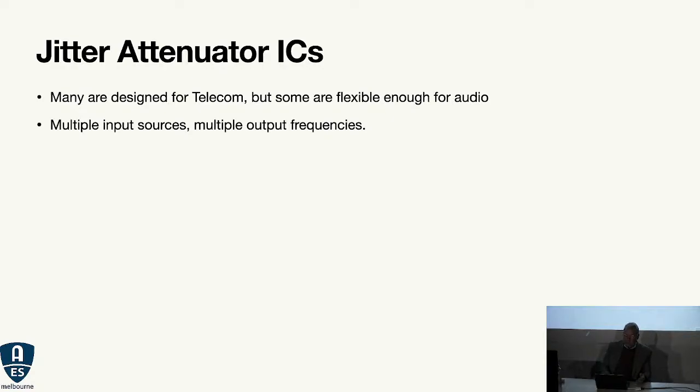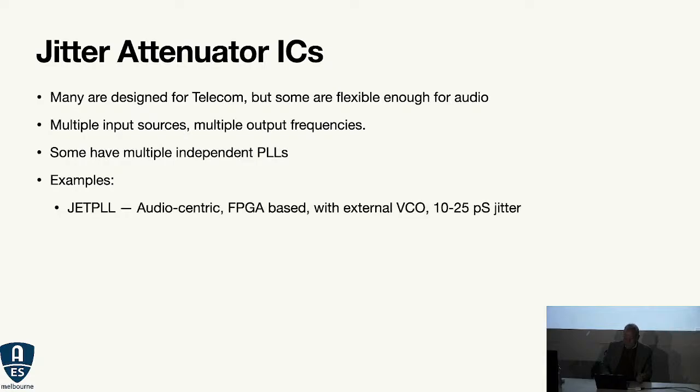These typically have multiple inputs, so you can select different sources. They have multiple output frequencies, so you can get all your different audio clocks out of one chip. Some of them have multiple PLLs that are completely independent, and that can do some interesting things that you might need. A few examples.